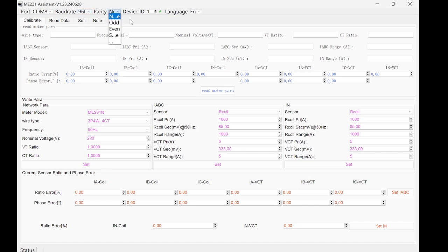It's a bit difficult here to read. I think it's just because my font size is too big. Then you set your device ID, and then you can click on connect. Also important is to select the right COM port, and I know it's COM port 8 from looking at my device manager. Then you can just click on this little green button there to open the port. And once it says here, status at the bottom, opened 9600 bit 1, then you know it's connected successfully.